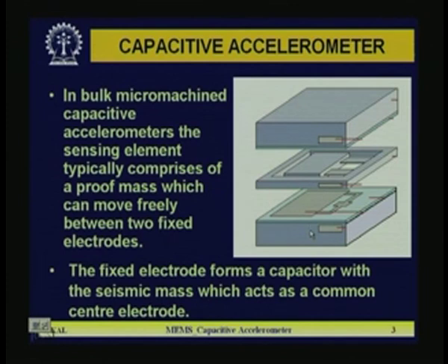In the bottom piece, which is fixed, a parallel plate electrode is configured, and you can take the contact from the side wall, or maybe some bond pads are exposed at the outside, from where you can take external connection. Similarly, the top fixed electrode also has a metallized plane which acts as an electrode.